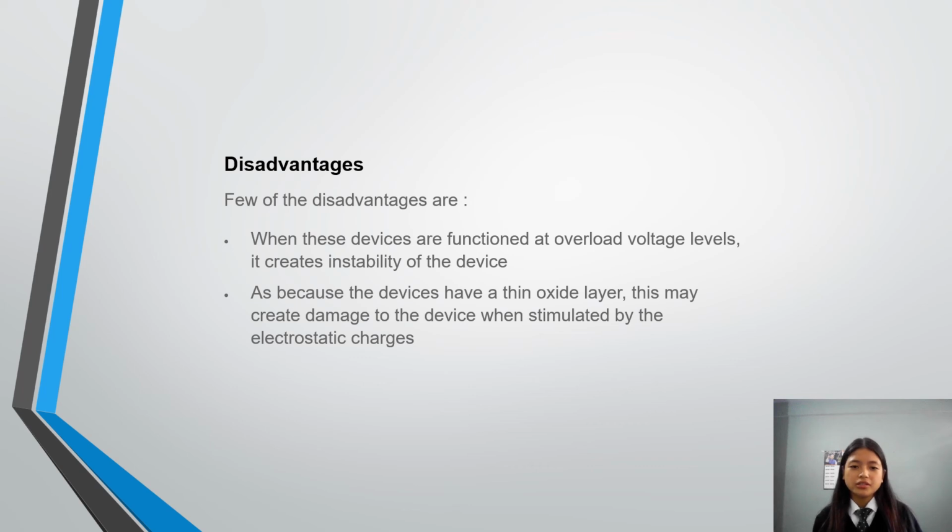Now, disadvantages. A few disadvantages are: when this device is functioned at overload voltage levels, it creates instability of the device. And the other one is, because the device has a thin oxide layer, this may create damage to the device when stimulated by electrostatic charge.